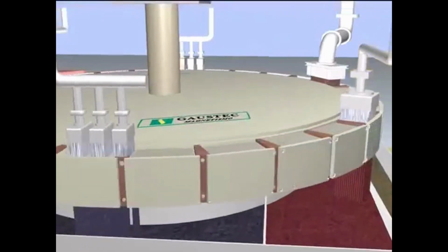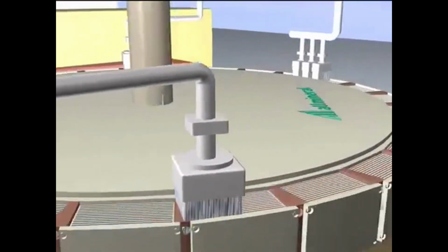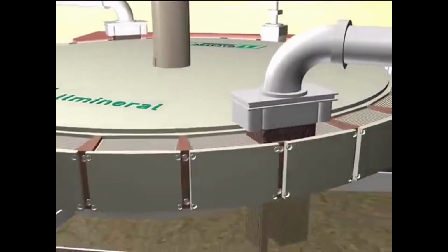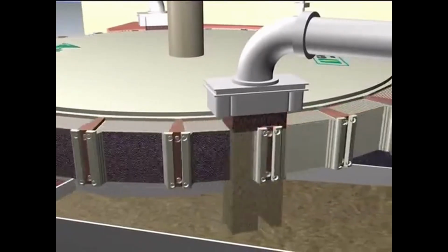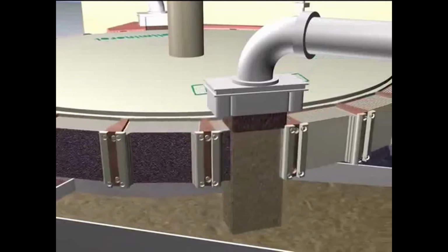And as you can see by the colors below, you have something like quartz exiting just at the beginning of the equipment. That's the feed, and below it the non-magnetic particles, the quartz, and then we have the middlings, and then we have the magnetic concentrate.